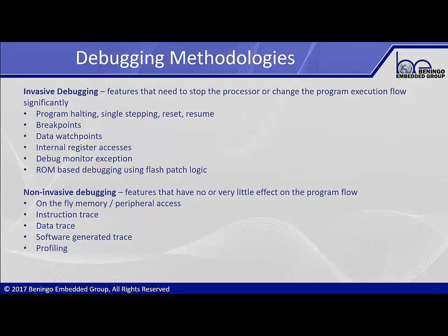These types of techniques, when using the trace tools, have been designed. There's hardware on the microcontroller that takes care of monitoring these events in these systems that then make it so that it doesn't interfere with the flow of our application. Non-invasive techniques won't affect our real-time performance, which is why I prefer to use them. I don't want my code execution behavior to be changing once I'm done debugging my system.